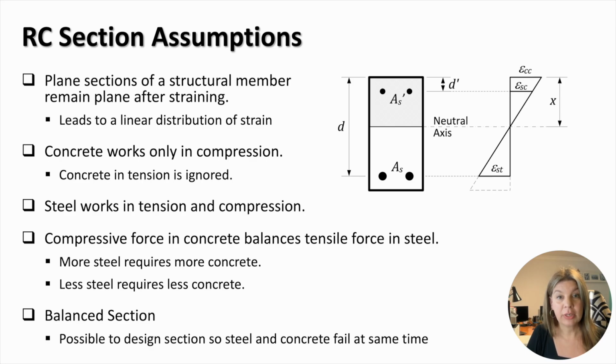Next, it is assumed that concrete works only in compression, and the contribution of concrete in tension to the resistance of the member is ignored. Steel bars work both in tension and compression. The design of reinforced concrete sections is carried out using forces and moments.